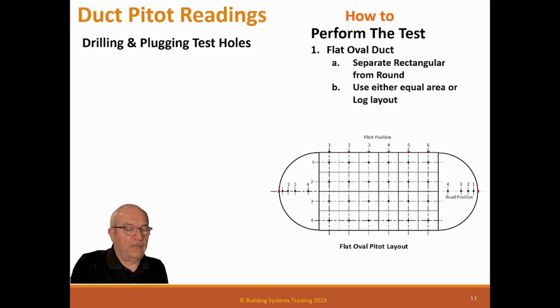Especially if you're working in an electronic manufacturing facility, you'll be really careful with this because on a lot of their exhaust ducts, it has acid in it, and this acid is very bad stuff. So you don't want to drill into that and get this stuff on you. And when you cut a hole in those ducts on the bottom, unless you cap them permanently, they could leak in the future. So basically, we try to keep our holes on top and on the side, but on a lot of air conditioning ducts, you can't get to the top, so you have to use the bottom no matter what. But no matter what, you have to plug the holes when you're done. You shouldn't leave open holes.